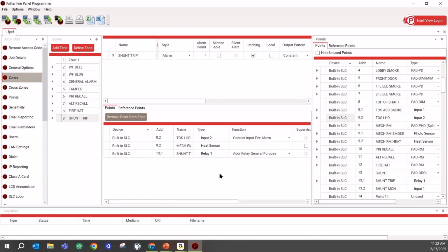Our heat detector has tripped. And we want to make sure that our heat detector trips at a temperature before the sprinkler head activates. So again, I'm going to put a big asterisk behind this statement. I have seen spreads of approximately 20 degrees between the heat detector and the sprinkler head. So if I've got a 135 degree head and there's a 165 sprinkler head in there, I've got 30 degrees. I think that that's appropriate.